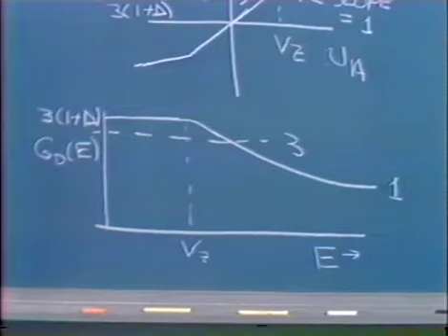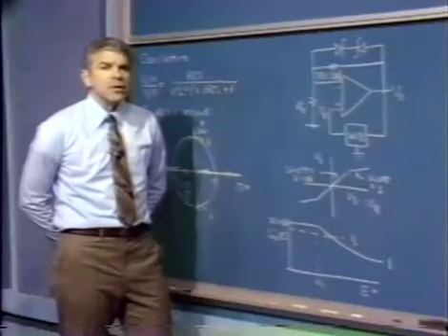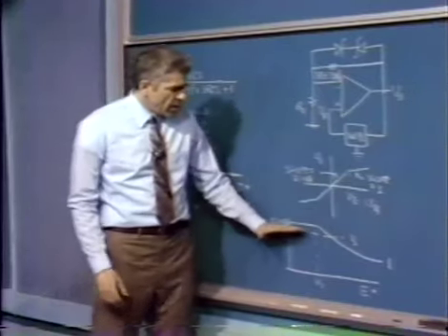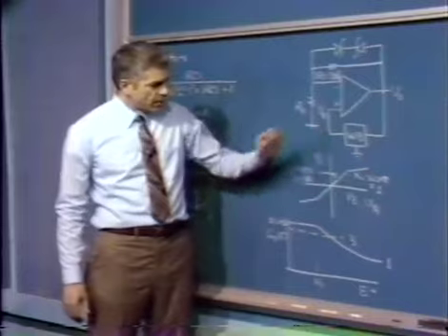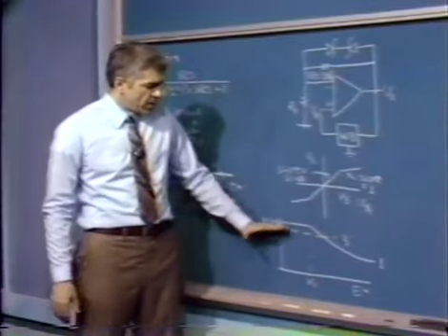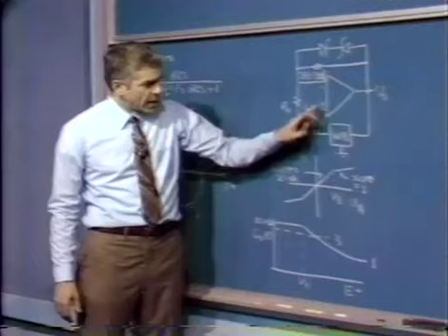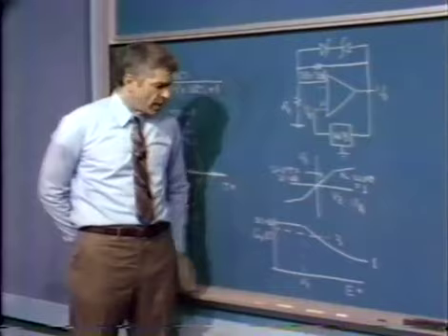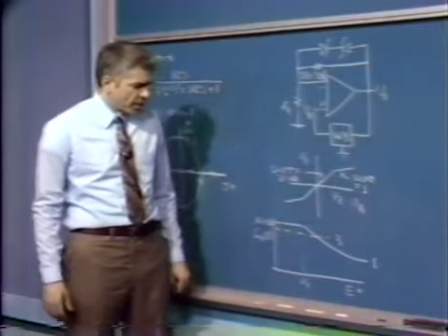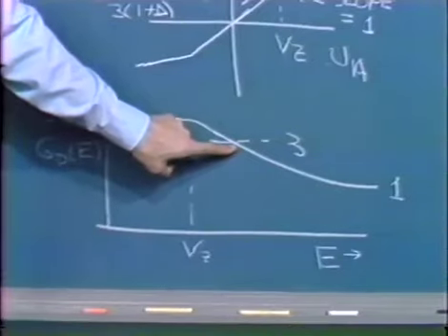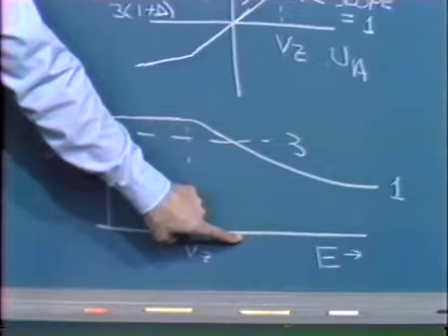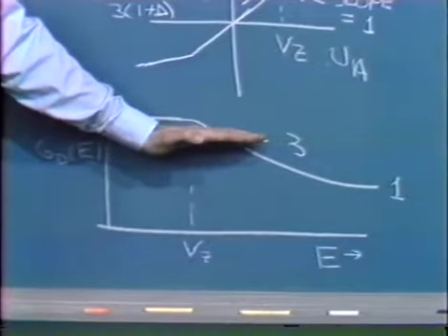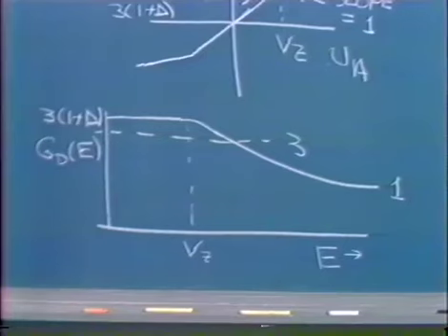And of course, we'd anticipate that our system would oscillate, assuming perfect components, symmetrical components in the Wien bridge, when the amplitude into our operational amplifier had become large enough so that the gain of the amplifier from here to here, in a describing function sense, lowered to 3. That's this point. So we'd anticipate that the amplitude of the fundamental component of the signal applied to the operational amplifier would be this value. That's the value that squeezes down the gain to precisely 3.